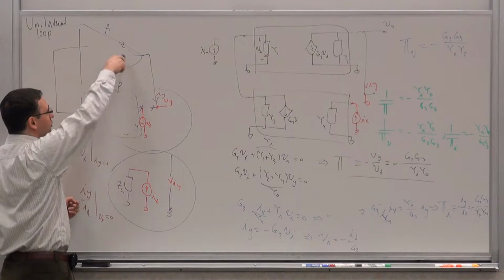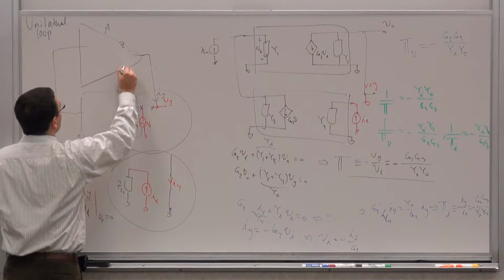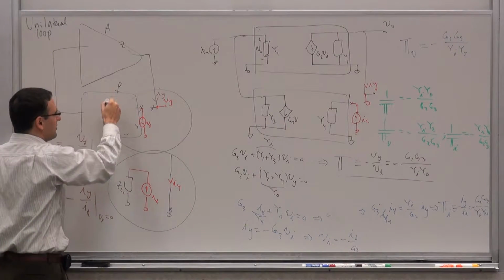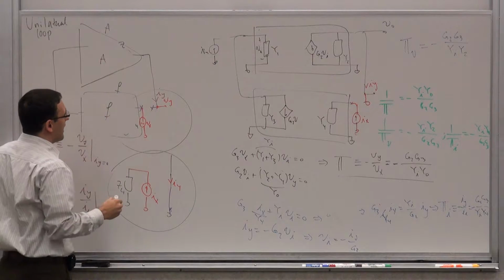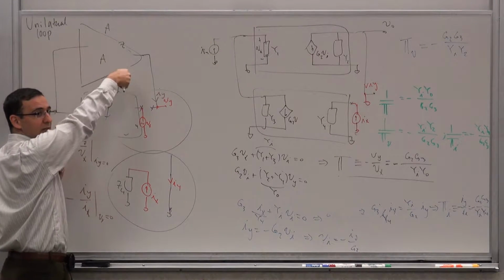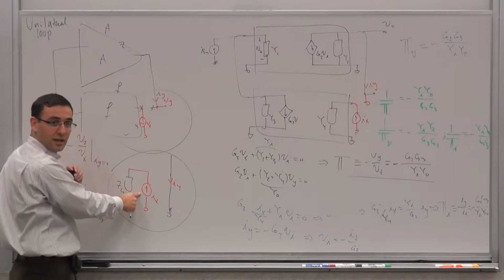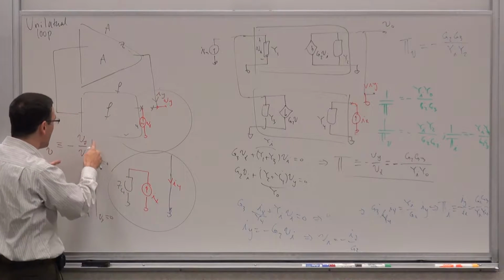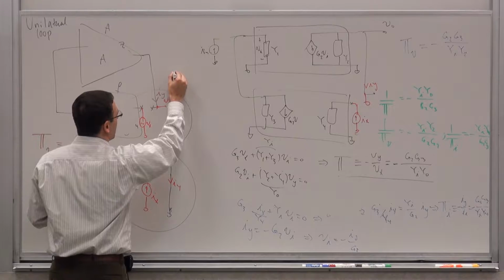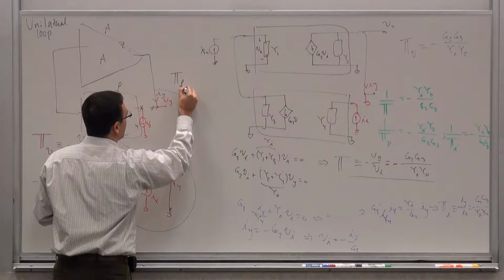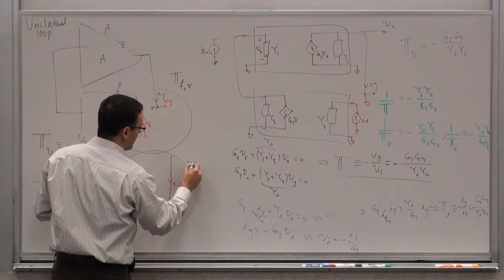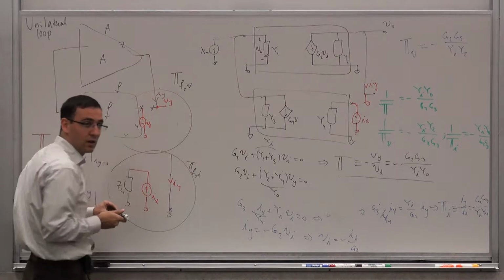Obviously, you have the quantities that we discussed. Let's say the desired loop direction is in this direction. Now, you could determine the voltage loop gain. We call this the forward voltage loop gain. And you could determine the current loop gain by doing this. So these are the forward voltage and current loop gains. This is TFV, and this is TFI, for forward.